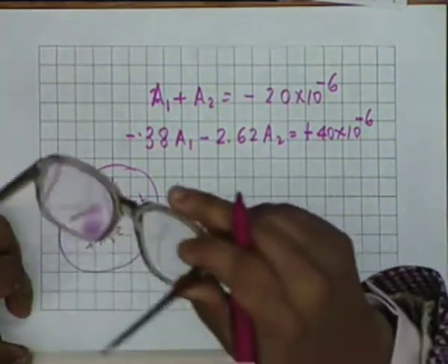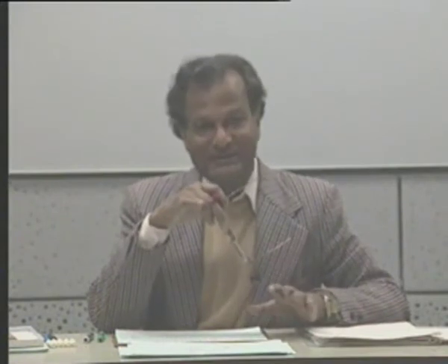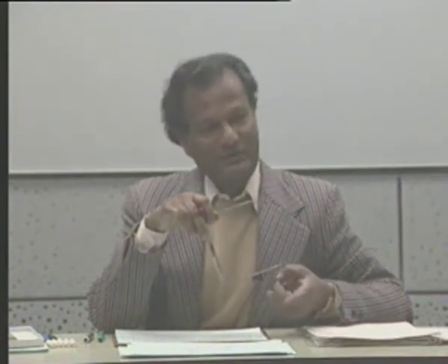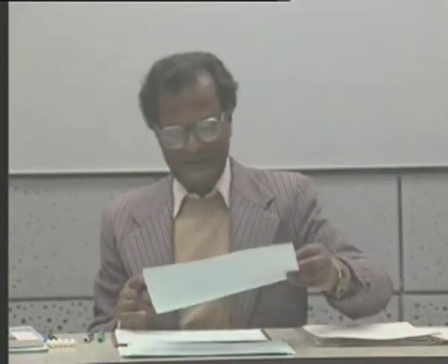If it's a capacitor, then you look at dV dt. If it's an inductor, then you look at di dt. But even that is not obeyed in this particular case, because we had to find out a di dt, and you shall have to think about this to be able to find the initial conditions. It would be a good exercise to try the previous two problems where I simply obtained the form of the solution and left the rest to you. It would be a good exercise to try the other two problems and solve them completely.